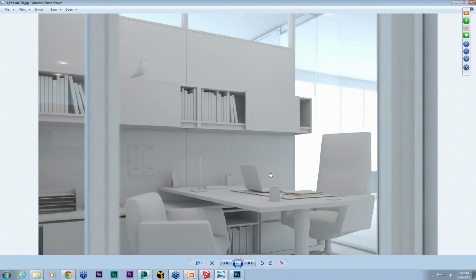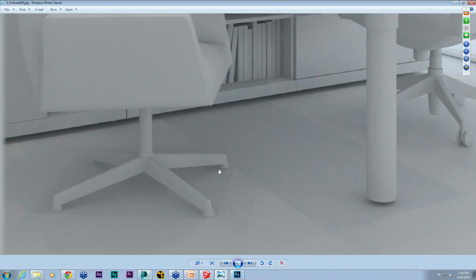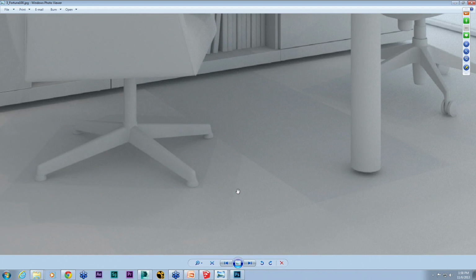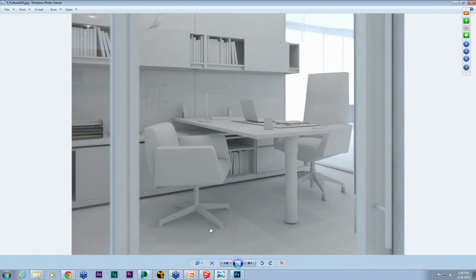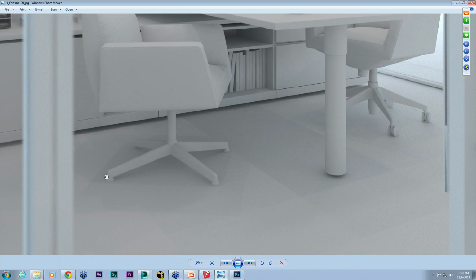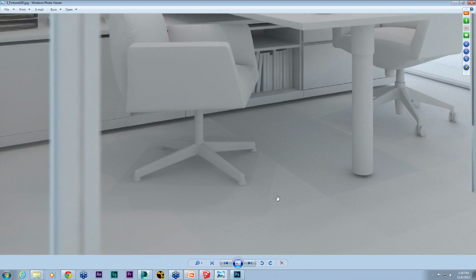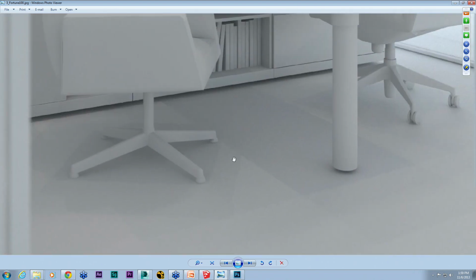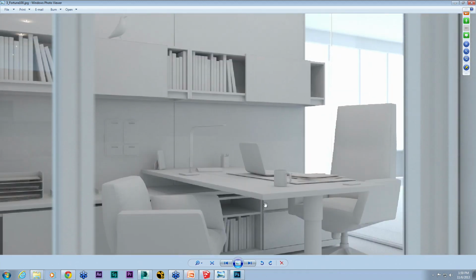One of the things that's really important for lighting on interiors is, I see some people like to use one big V-Ray square, but that doesn't give you the nice multi-shadow, like right around here, that you would get from multiple IES lights. Yeah, the contact shadows are really important. Yeah. And even though they're crisp, because there's multiple ones, it kind of softens it out. It's a nice effect.